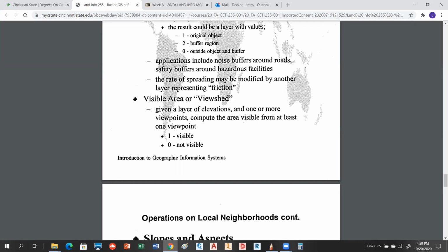Cell towers are very often sited based on viewshed technology, because they have to put a cell tower at a certain height and at a certain location that gives you the most coverage. And even so, sometimes you have dead spots. That would be the point where you can't see line of sight, because radio waves basically have to be line of sight. Okay, so viewshed technology is a pretty neat thing.